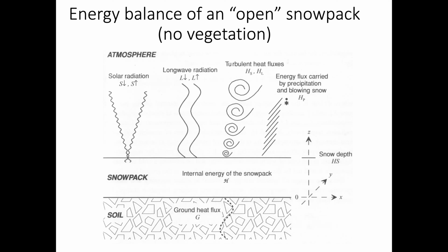Moving on, rainfall energy can influence the snowpack energy budget in three ways. First, relatively warm rain can add sensible heat. Second, the release of energy called the latent heat of fusion occurs if the snowpack is below zero and the rainfall refreezes. Thirdly, condensation can occur on the snowpack due to high humidity associated with rainy weather.